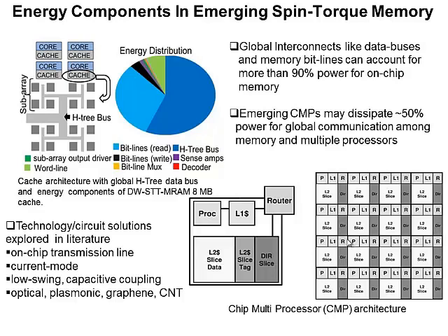So if you look at the general cache architecture, it has an H-tree-shaped data bus, which is used to access the individual memory arrays. And in each of these memory arrays, we have bit lines which are used to charge and discharge based charge reading operation. So since these are the global metal lines, their charging and discharging constitutes most of the power consumption in such a non-volatile memory.